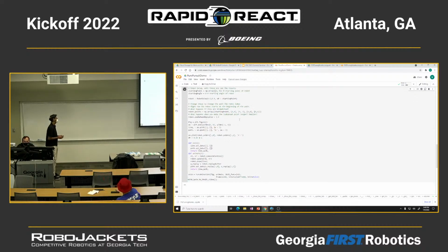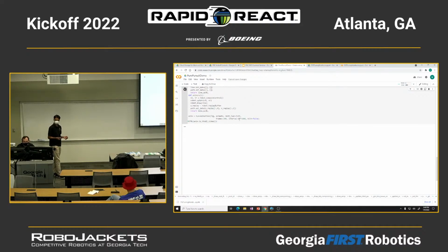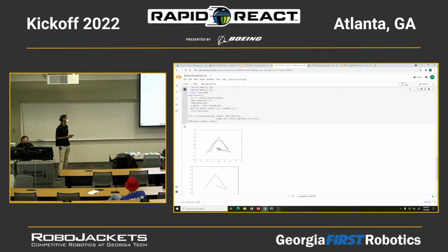Well, let's find out. For those of you watching on the stream, the general consensus is that people think the robot is going to be farther away from the path. And you would be pretty much correct. One key thing to look at is that the robot is going to make much wider arcs when it turns, so the robot will start turning earlier. It'll make a wide turn, rather than with a short look ahead distance, where it'll make a sharp turn.